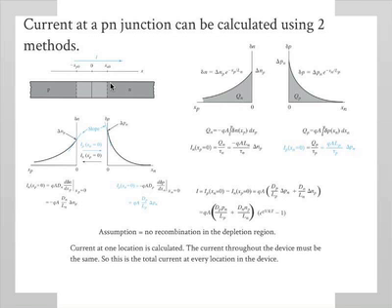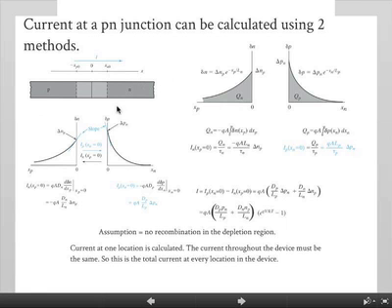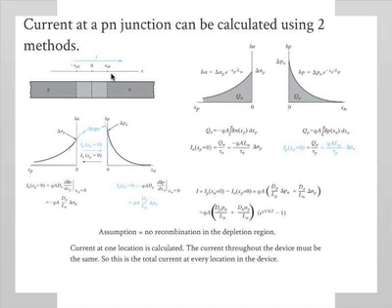And that exponential decay is the steady state distribution. And what you want really is how do you relate this to the bias potential. The bias potential, of course, increases this injection because you're reducing the energy barrier. So remember, here there was an energy barrier which we talked about last time. When you forward bias it, you reduce the energy barrier, you have more carriers that get injected. So that's how current increases. If you reverse bias it, you increase the energy barrier, fewer carriers get injected, current decreases. That's the picture you need to keep in mind.